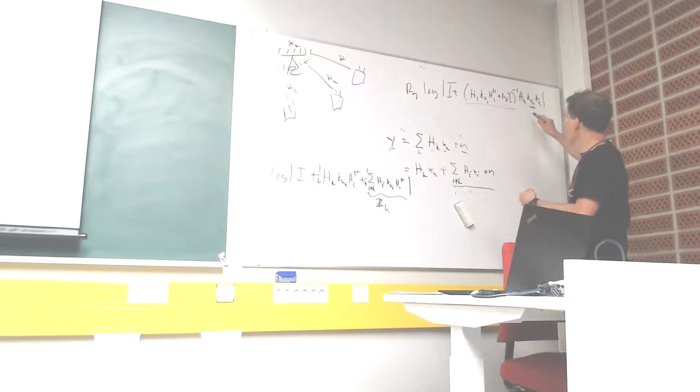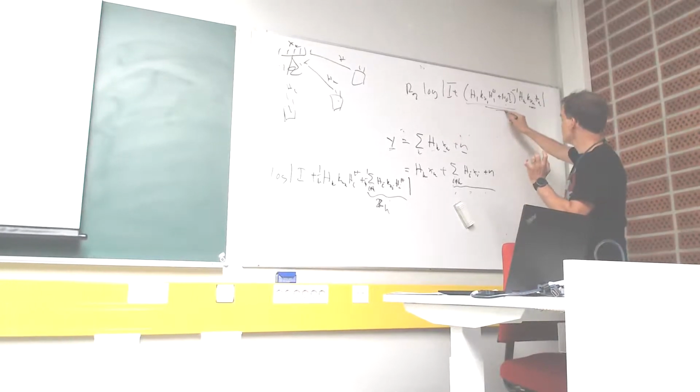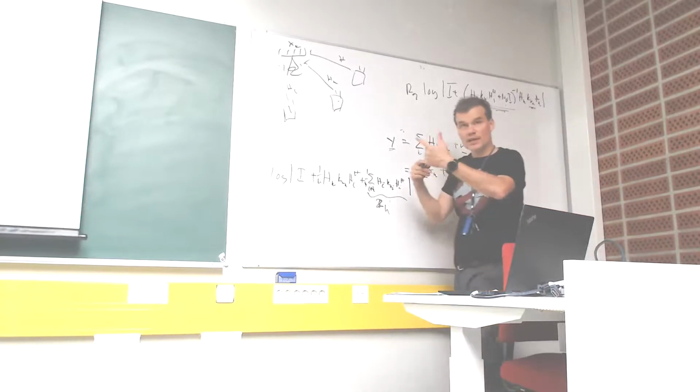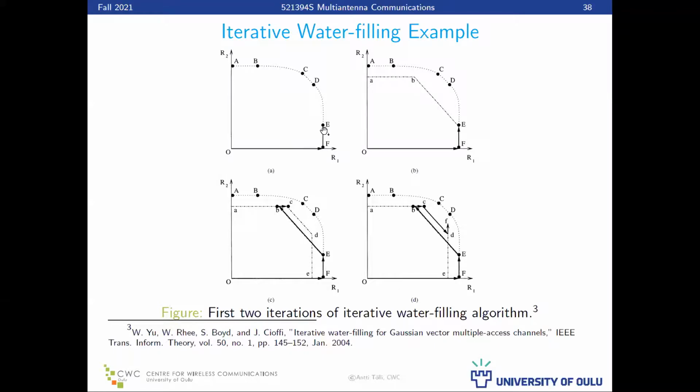So when we optimize Kx2 given the fixed interference, using the water filling process, that is right here. This is the rate pair you should use when you compute these two extreme points for the rate region, giving absolute priority to user 1.